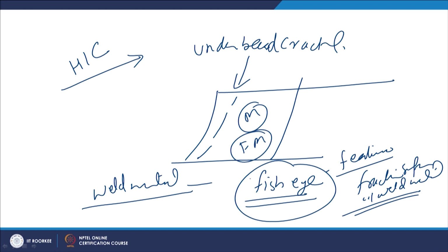So, in order to control the weld metal cracking, basically the low hydrogen electrodes we can use, and we can also do the preheating of the base metal, so that the weld metal gets enough time for the solidification, and then the post weld heat treatment by prolonged exposure at elevated temperature of the entire weld joint helps in escaping of the hydrogen from the weld metal.